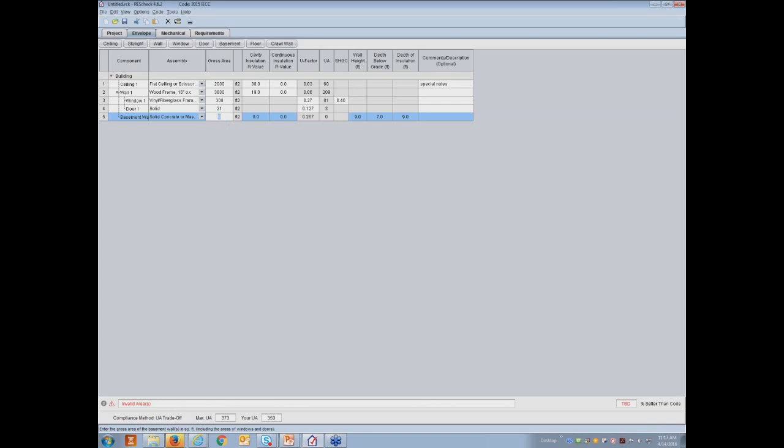For this one, of course, it was quite easy. I hadn't entered the square footage for my basement walls yet, and then what I'm insulating my basement walls to. So if I'm furring them out and I'm putting in insulation in between the structural members, it would be cavity insulation, and I'd enter it as cavity instead of continuous.